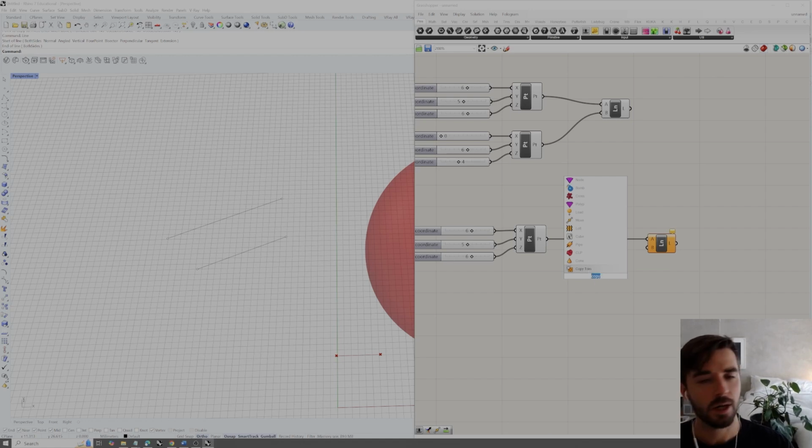So because they're virtual references inside of Grasshopper, we don't actually need to specify that we're copying versus moving. We can actually just move the geometry and reference the original and the move geometry, meaning we actually do get a copy just by moving. So I'll kind of prove this and maybe it'll make more sense once we do. So if I type move here, we can get access to a component which says translate, move an object along a vector. So this is where vectors are incredibly important.